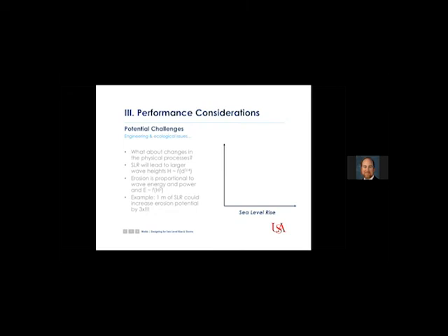Other potential challenges that we don't often think about are the changes in the physical processes. Sea level rise leads to larger wave heights, because if the water depth is going up, generally wave heights scale as water depth to the 3/4 power, and erosion is proportional to wave energy and power, which is a function of the wave height squared.